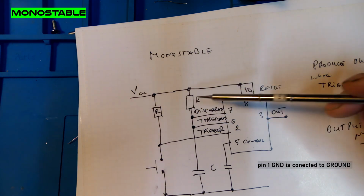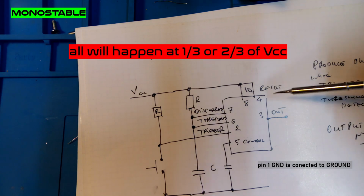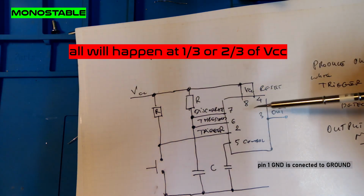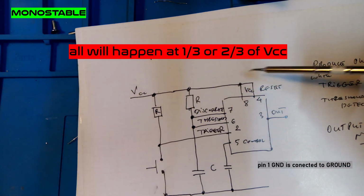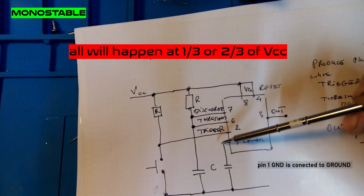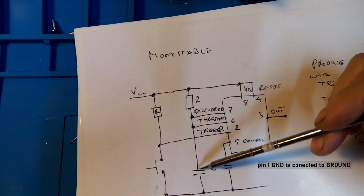How does it work? As we know, everything changes at 1/3 or 2/3 of VCC. When the trigger input is above the trigger level and the threshold input is above the threshold level, the flip-flop is reset and the output goes low.